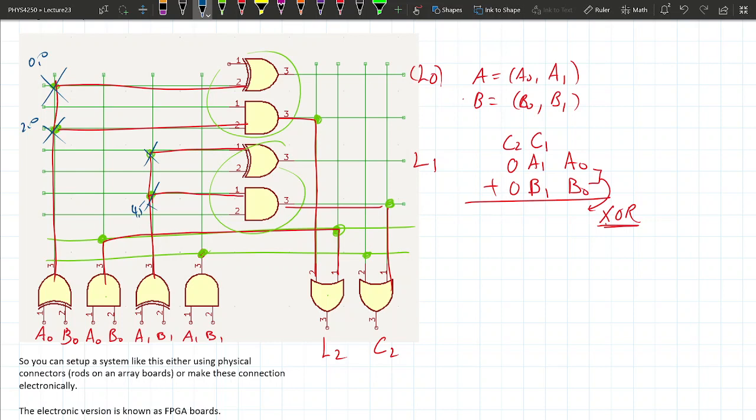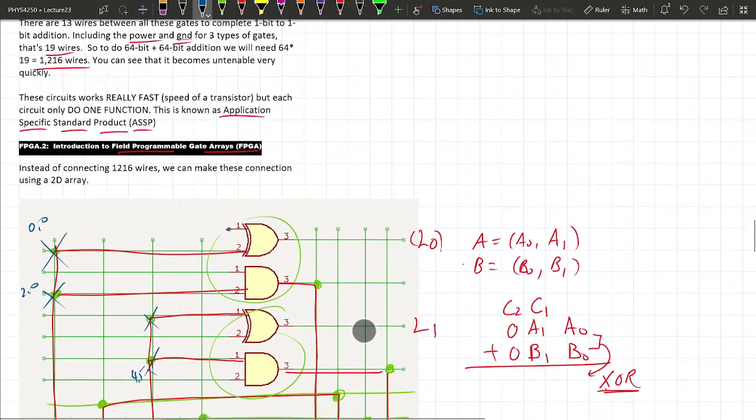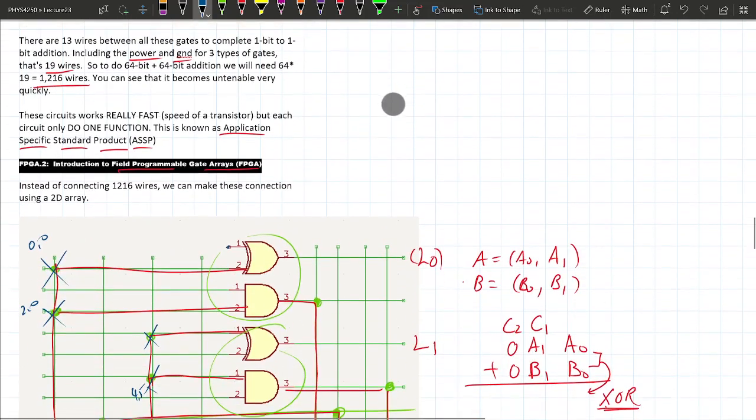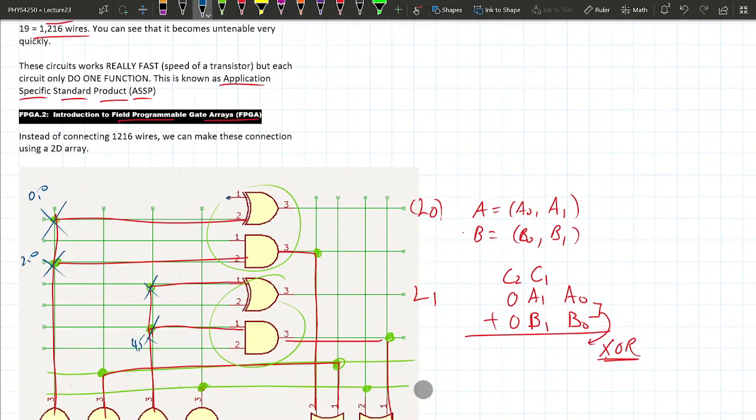Some of those inputs are not connected to anything. So all the inputs here are not connected. Oh, maybe you're thinking about this one? Yeah, those ones. So what is this up here? If we go back to our diagram up here, what is the input for the second OR gate in our full adder? What should one of the inputs here be? Carry in. It's the carry in. But what's the carry in for the ones place? 0. Right. So it should always be ground.